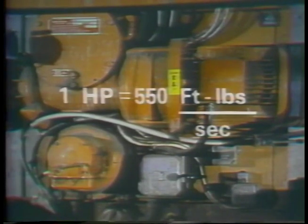Now, to convert the 5,000 foot-pounds per second of power into horsepower, we use the conversion factor 1 horsepower, HP, is equal to 550 foot-pounds per second. To do the conversion, we divide 5,000 foot-pounds per second by 550 foot-pounds per second per horsepower, and we get approximately 9.1 horsepower. This is the horsepower needed to move the load and the elevator 250 feet in 60 seconds.